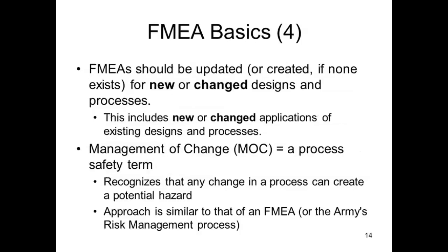FMEA should be updated or created for new or changed designs and processes. That management of change is worth remembering. It's originally from process safety from the chemical process industry, which says any time we change a process, it can create a potential hazard, and a change can involve a startup.